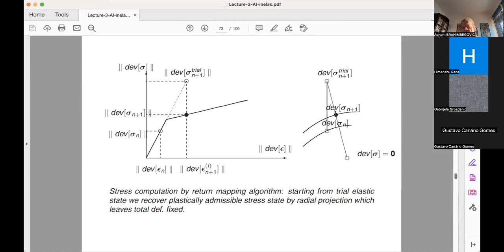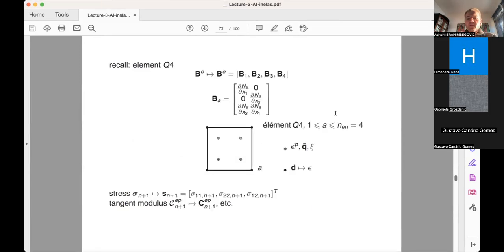You cannot go wrong. All these circles, if you have isotropic hardening, are just getting bigger and bigger due to the hardening. And then when you're projecting, you come back and they're all concentric, they all have the same center. So if you go outside, you just project down to the center and you find this point in one shot, without any difficulty. So this is the kind of illustration you can have. It's still 3D plasticity, but the illustration shows clearly that there's only one mechanism there.